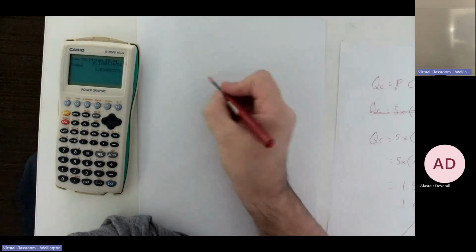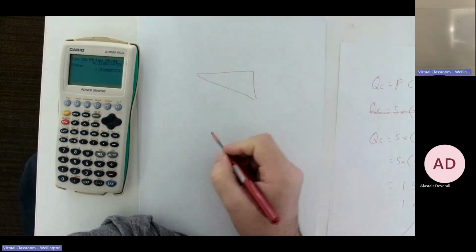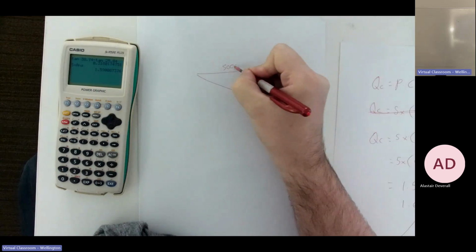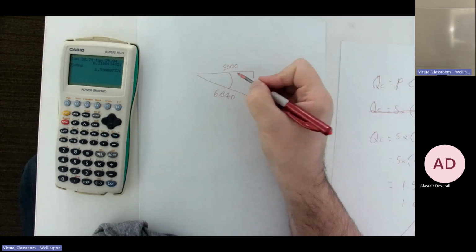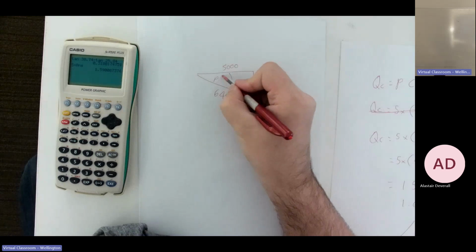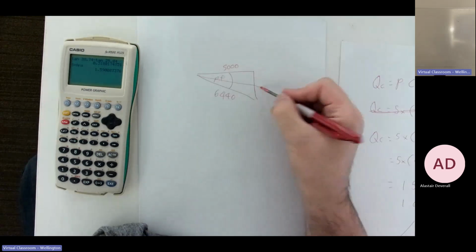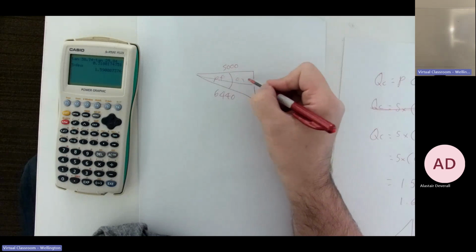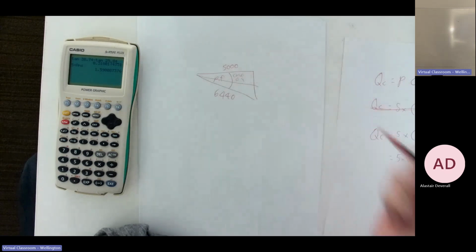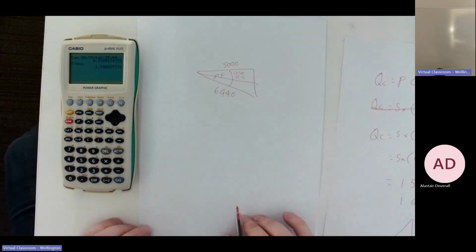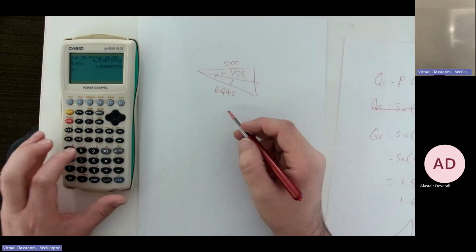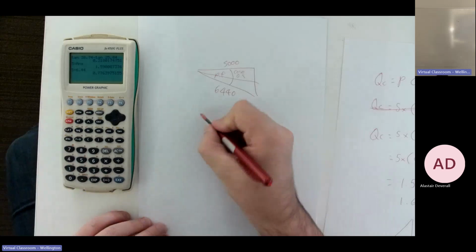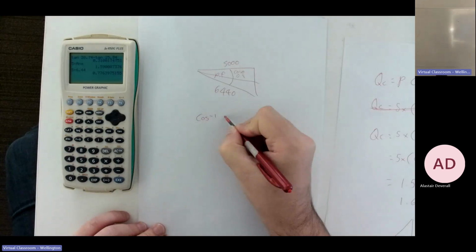So we may as well test that out, because we've got our values here of 5, 6.44, and we've got our existing power factor, and then we can throw in our new one, which is going to be 0.9 when we do the cos theta on it. So going into our maths, we end up with 5 divided by 6.44, and then cos to the minus 1.